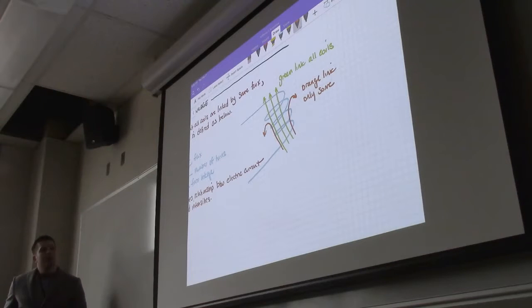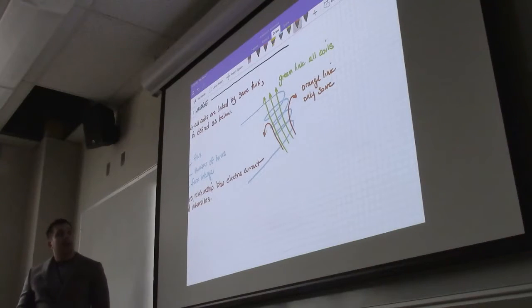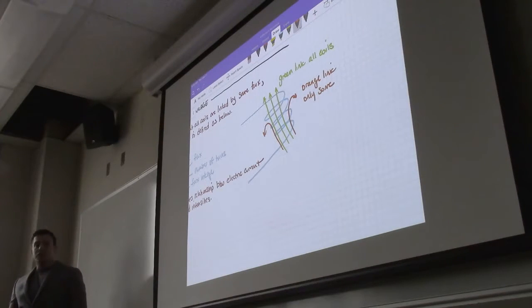If we have flux lines that are leaking into the air and it's not equal, I mean, we don't have the same number of leakage lines per chunk along the way here, then our assumption wouldn't hold.